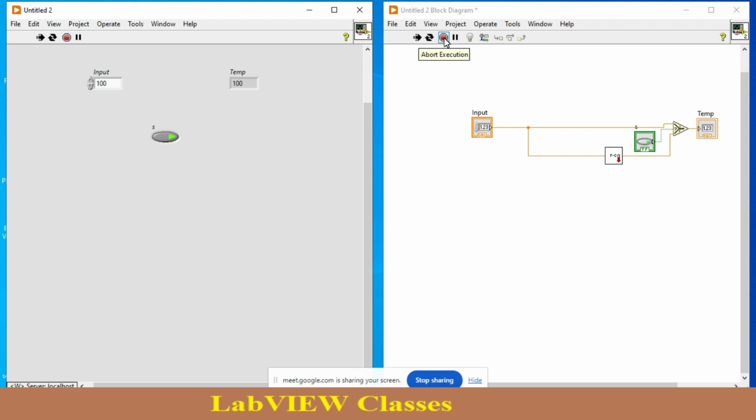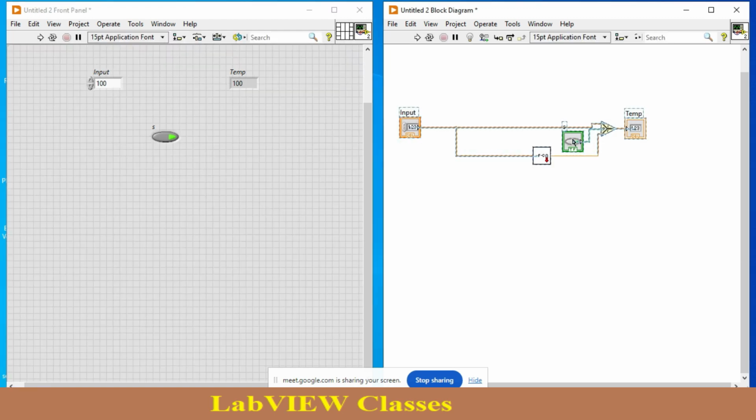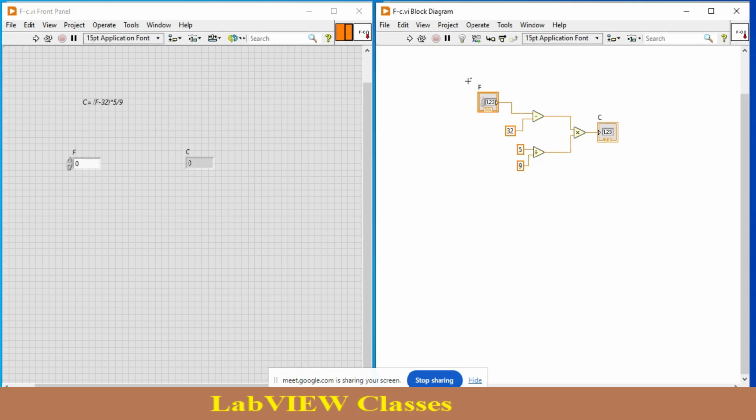So this is an example of again a select function and also modular programming. We also call sub-VI modular programming because we can drag this function multiple times in our VI. It is up to you. You need not create an in-between function; this function will replace that function.